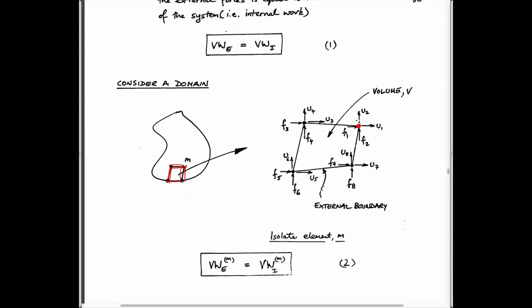It's either a flux or a pressure or a head that is defined behavior. Both of those quantities, head or flux, are scalar quantities, but deformations and forces are very much vectorial quantities. A force has a direction and a magnitude. And so in 2 dimensions, each of these nodes would have a displacement in the x direction, a displacement in the y direction, and also an equivalent force in the x direction and a force in the y direction.